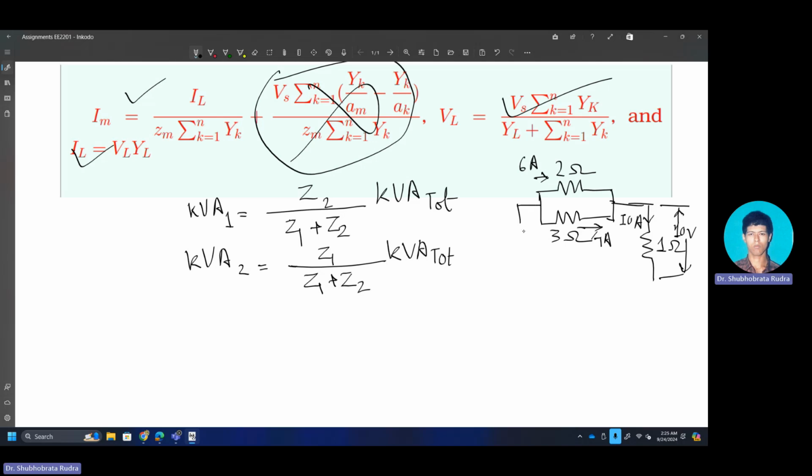Right. And on this side, you have one supply. That supply must be strong enough to support this. So the supply voltage should be, if there is no further one, how much? It must be 22 volt, because in this branch you have the drop. Now consider how much kVA is being transferred here.